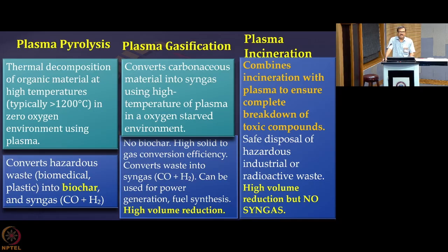So, there you will see that hazardous wastes are no more hazardous because all bonds are broken, but it will form biochar because oxygen is in a very limited quantity. They are combining with the oxygen. If it is there, they are forming CO and H2, but not all carbons are getting enough chance to form CO, so they are staying as biochar at the bottom.